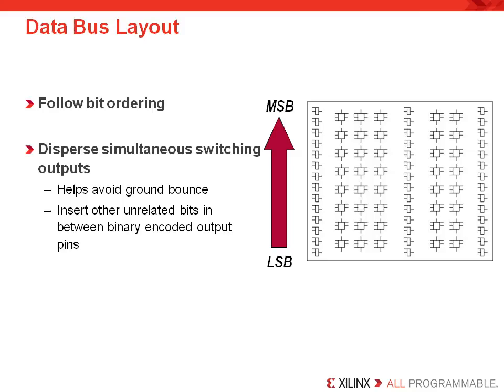Likewise, recall that to reduce the chances of suffering a ground bounce problem, we need to manage how many pins we have for each I/O standard in each bank. The noise analysis tool included with the I/O Planner is your best means of analyzing the situation, but try to remember that dispersing at least some of your pins that may transition at the same time is always wise, so you'll have to plan that for yourself.